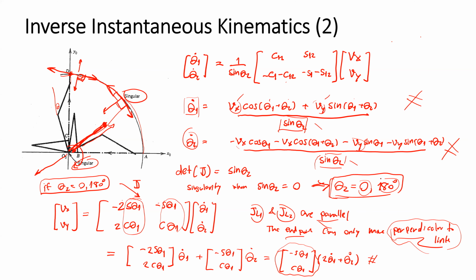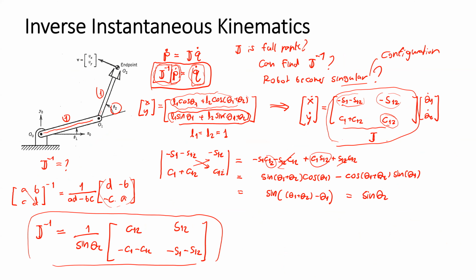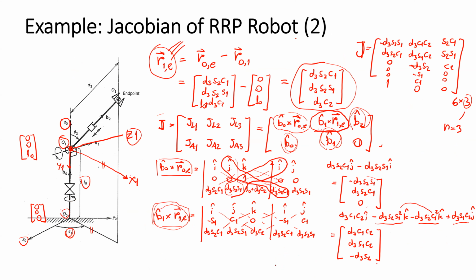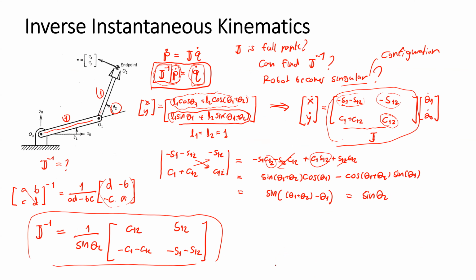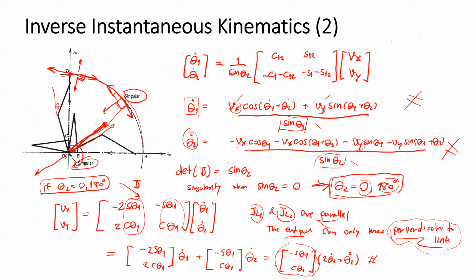We saw what the inverse Jacobian is and what its application is. We saw one simple example of how to derive the inverse Jacobian for a 2x2 Jacobian matrix. We had a short introduction about the meaning of the singularity point when the determinant of the Jacobian becomes 0.